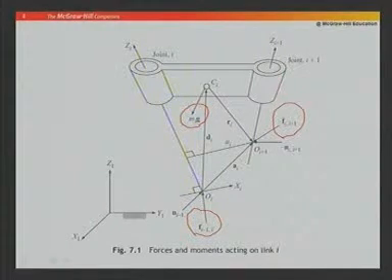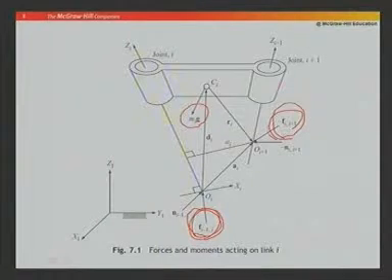If I say F(i-1,i) is towards the ith body, this is one force, then this is another force. So I can write F(i-1,i), this force, plus this, which is actually minus F(i,i+1), plus m_i g should be equal to 0 when it is in static equilibrium.